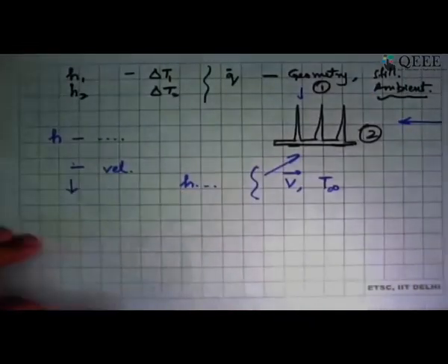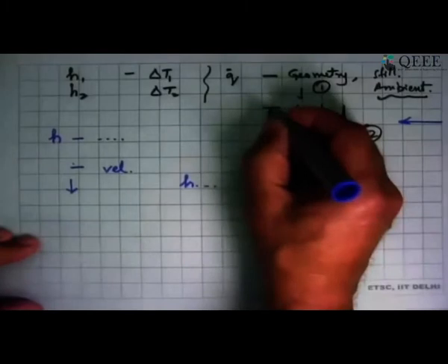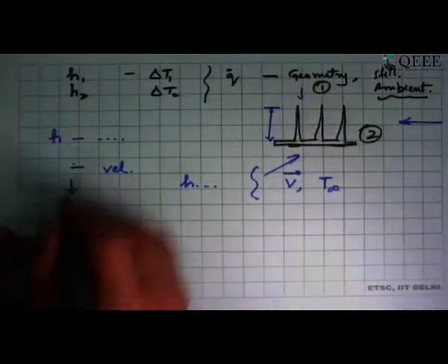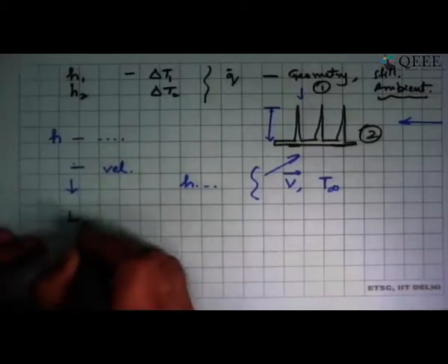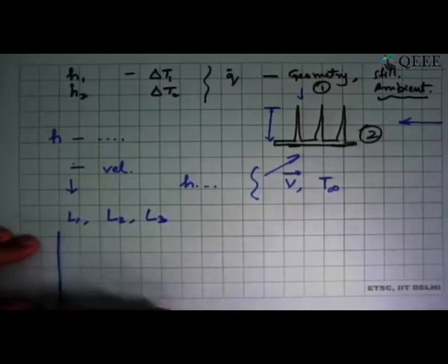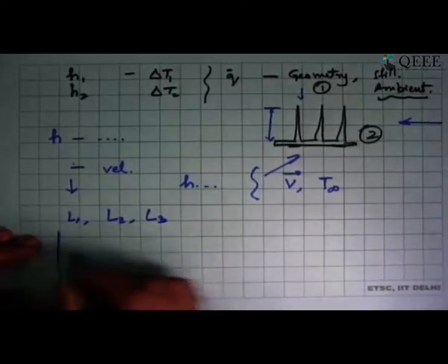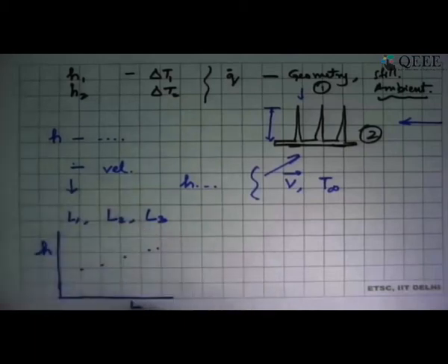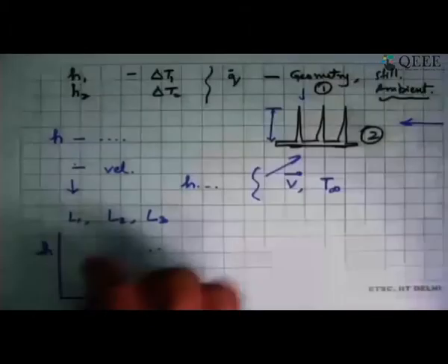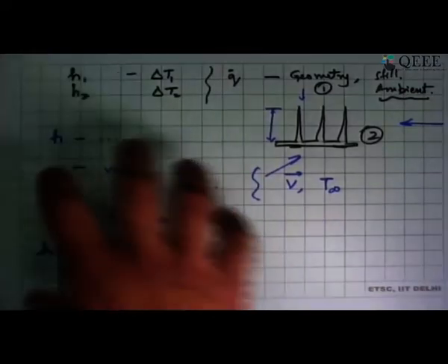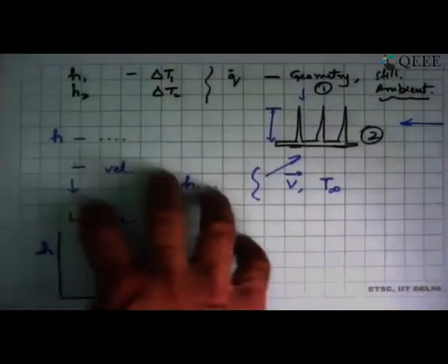Then we could generalize this further and say that, look, I have done a series of experiments for the length of the fin. So this is a correlation for L1, this is a correlation for L2, this is a correlation for L3, and then we can make a plot and say that, look, if your length of the fin is this much, then what is the h that you can expect? That becomes another chart which the designer can use. And so if we have to solve a problem, or you have to design a fin, this is what we will use. We will not go back and do all these experiments all over again. Okay, so this is an example of the experimental approach to what happens.